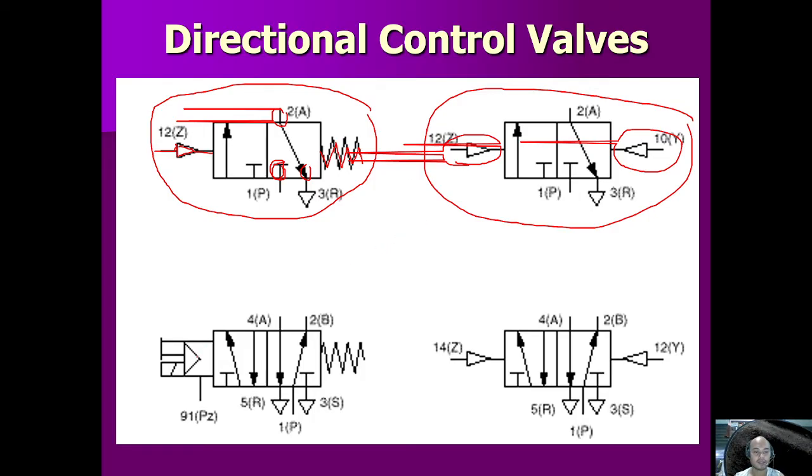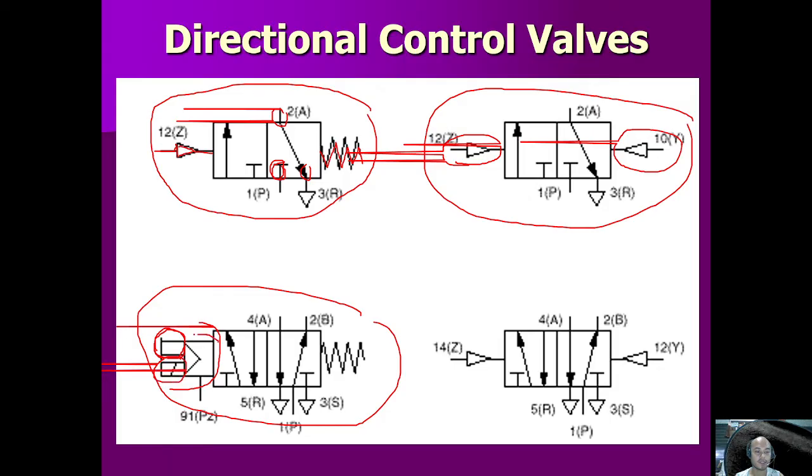Okay, next here we have a 5 2-way valve. There are 5 ports with 2 positions, and normally open. And here I think this is general, so it is manual activation, and we have also another activation here which is solenoid. And in this one, I'm not sure, since it has PZ here, so maybe it is piezoelectric, so it is like a solenoid.